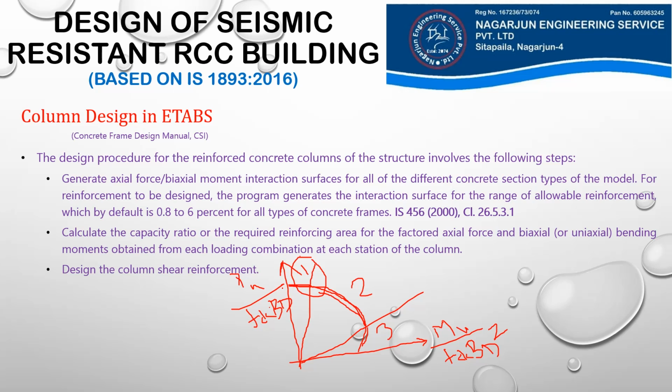We see that there is a high value of axial load in this region and a very little value of moment. In this region, the column is designed primarily for axial load, and we only consider the minimum moment that arises from the minimum eccentricity criteria. So the columns designed in this region will have minimum moment carrying capacity.